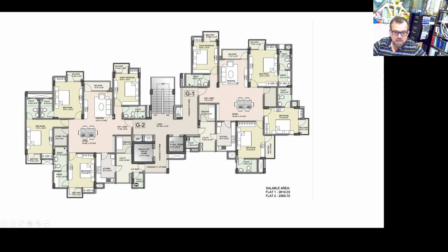I don't see straight lines except this part here. Now, why are these columns in this direction with the biggest inertia in this direction, and not in this direction? That is part of the preliminary structural configuration that the engineer has to create.